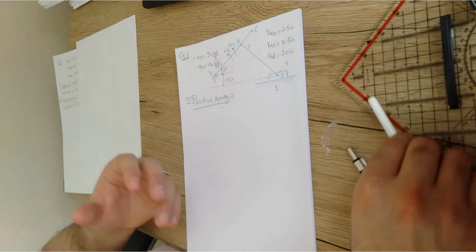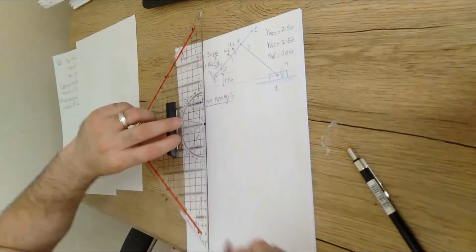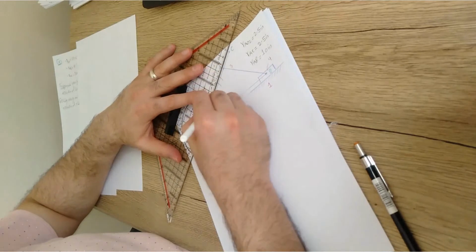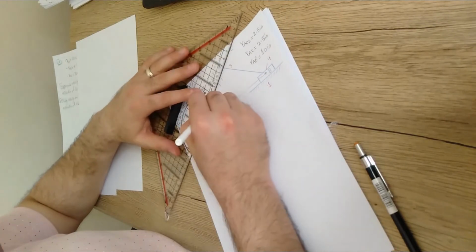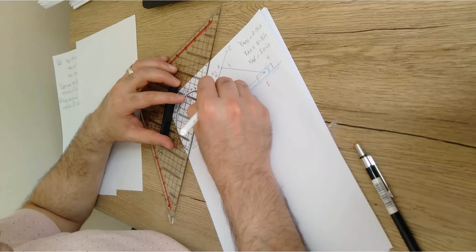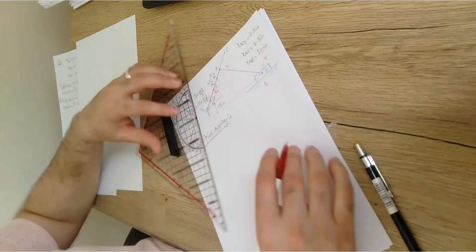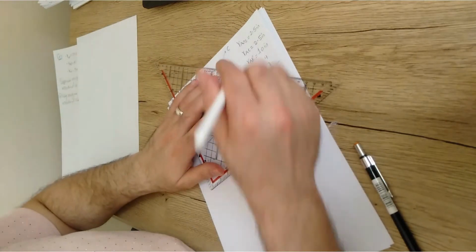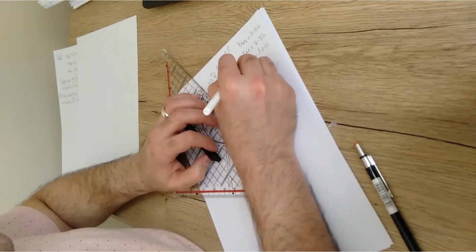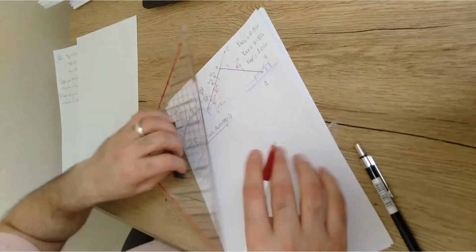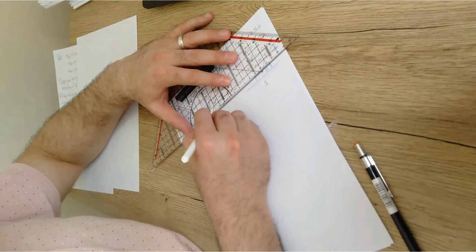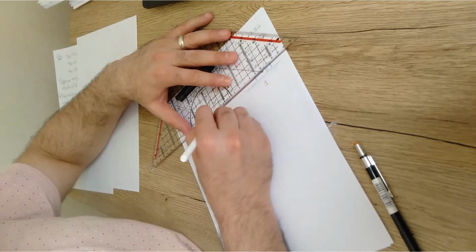Then what we're gonna do is just to set up the position vectors as we usually do. So starting from O2 to A, this should be position vector 2, right? So let us assume that this is the R2 vector. And from A to B, we have the R3 vector, which is this position vector. And definitely we have to set up a position vector for the slider. This slider is moving over the horizontal direction.